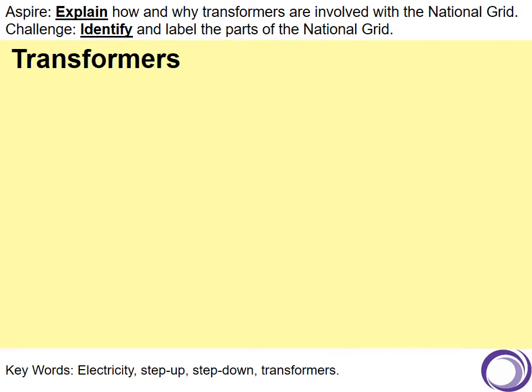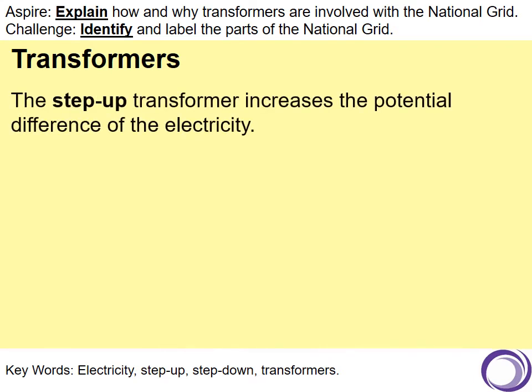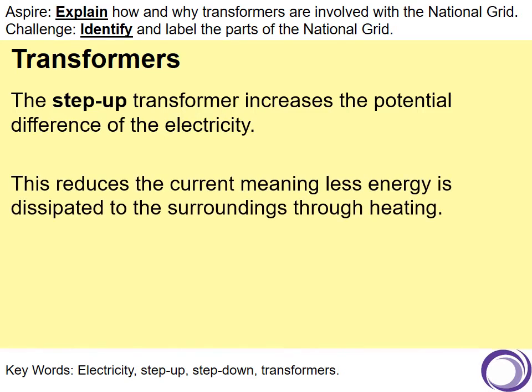Okay, then just to summarise, transformers are based around efficiency and making a more efficient system. The step-up transformer increases the potential difference of the electricity. Remember, we're trying to keep the power the same, so if you increase the potential difference, you need to reduce the current. This means less energy is lost and dissipated to the surroundings through heating of the electrical cables.